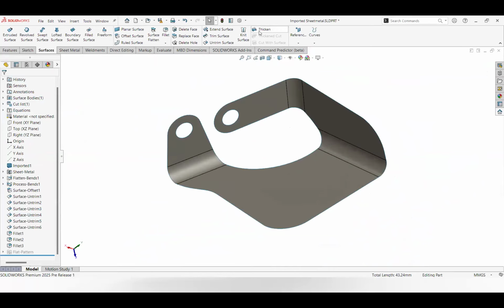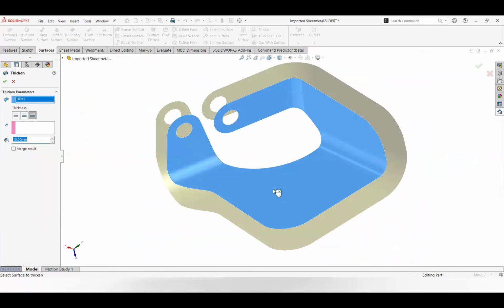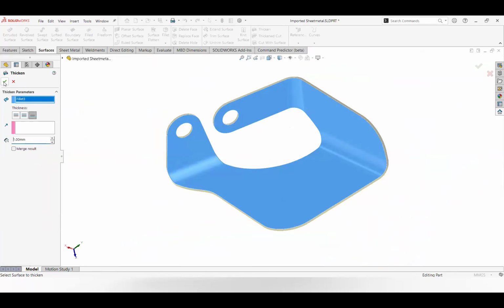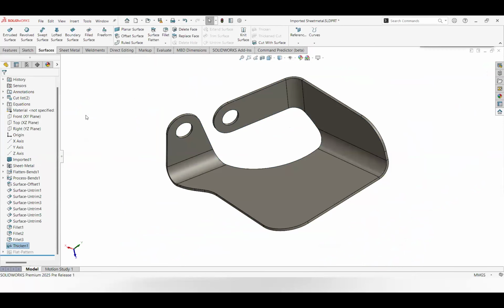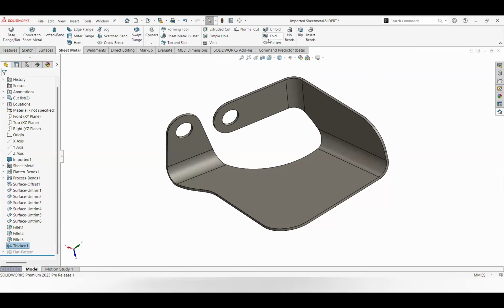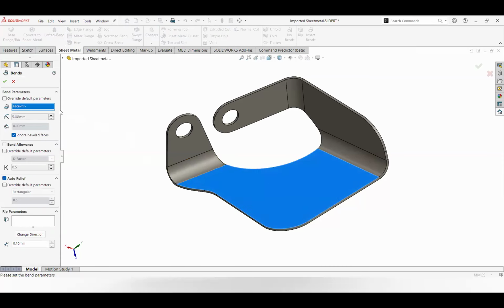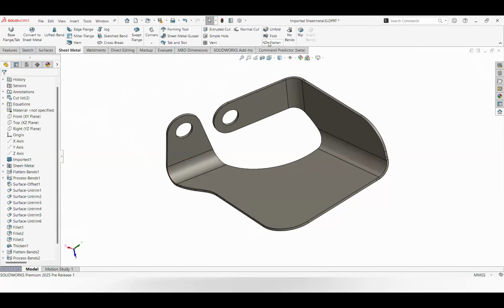Yeah, but from here, you can take any surface and thicken it. This is also a really slick way to deal with a bunch of other modeling conditions when you just need the geometry to be thicker somewhere, thinner somewhere. You can thicken and cut, you can thicken outward, and now the sheet metal features work just fine to say, hey, insert bends in this thing. Because now it knows these are all 5mm radii, right?